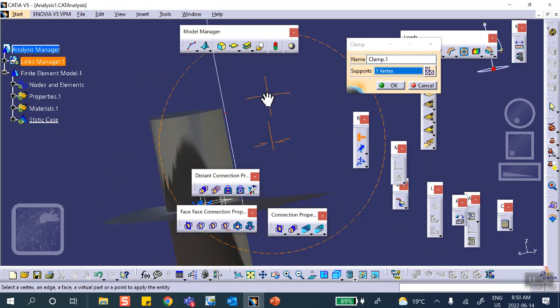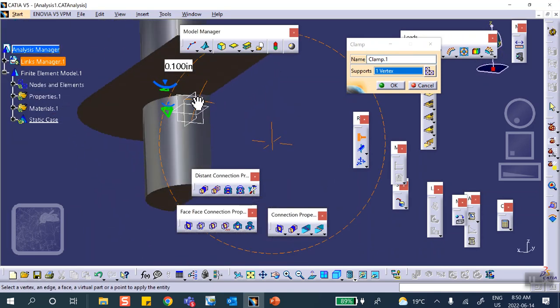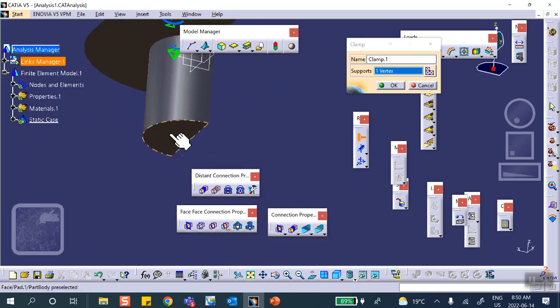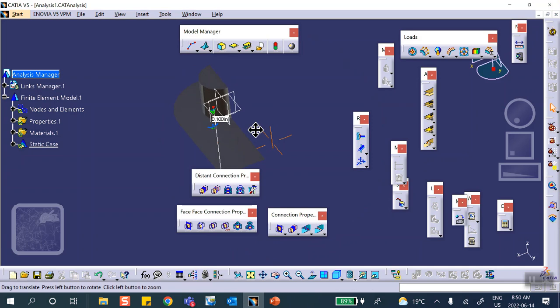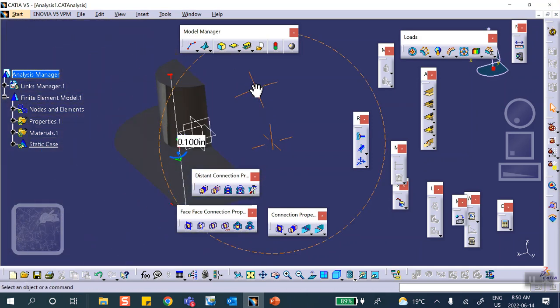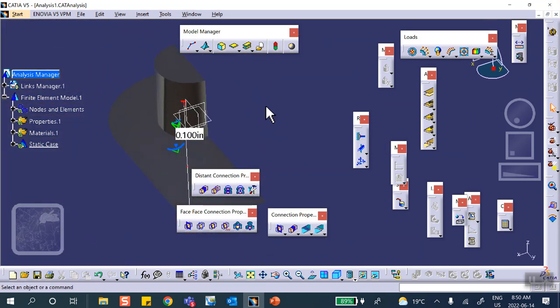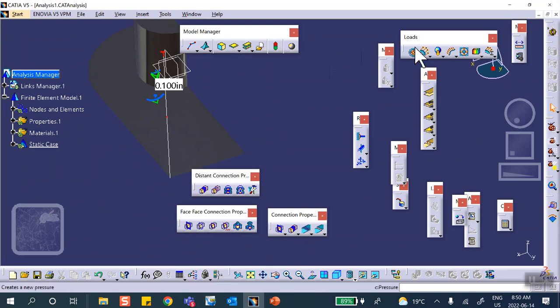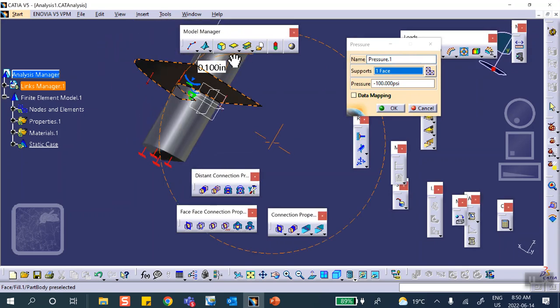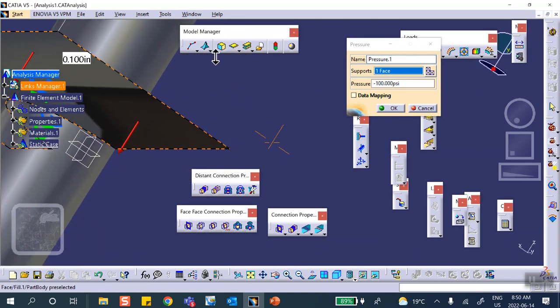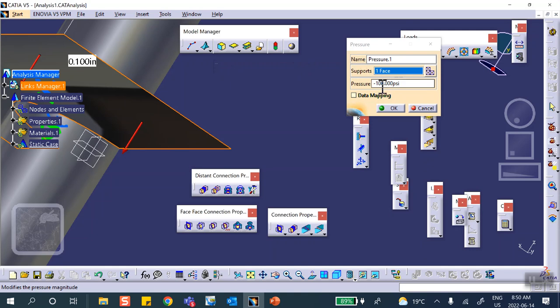Okay, we also have this bottom. In this particular problem, I can lump them in the same one. You don't have to. You can do a different clamp. But there's 2 things. The top is clamped. You see that? And the bottom is clamped. Okay, good. Now let's pressurize this. I'll put some pressure. Make sure that the direction is correct. This is correct. Pushing down. Okay, that's why I needed this minus sign here.